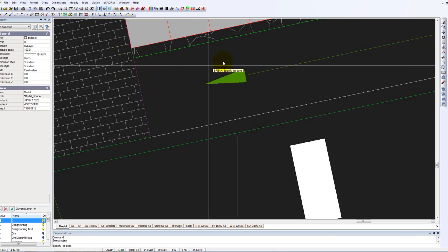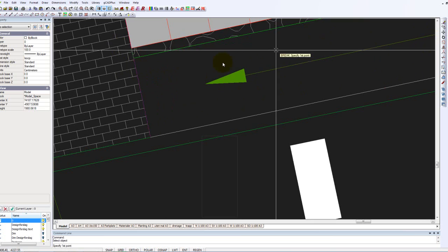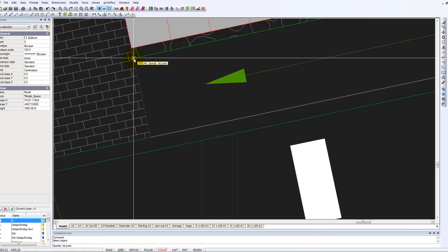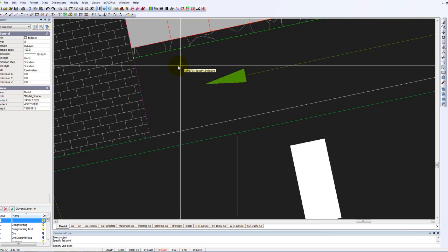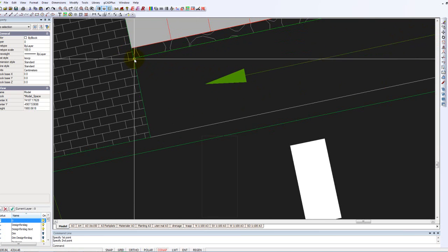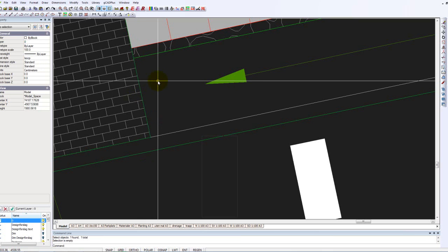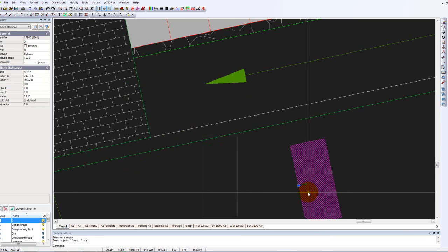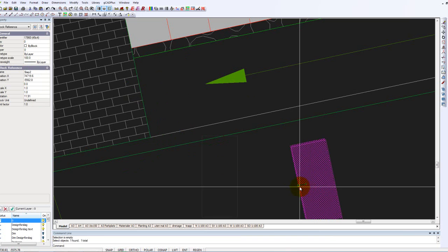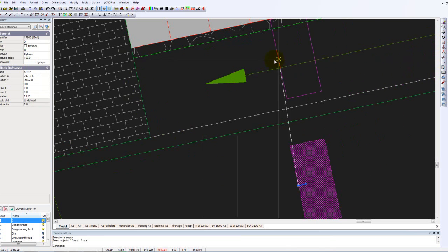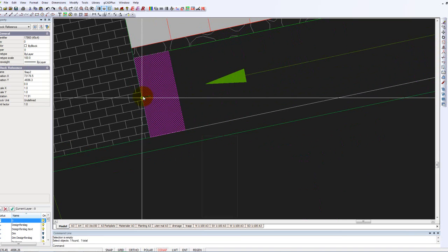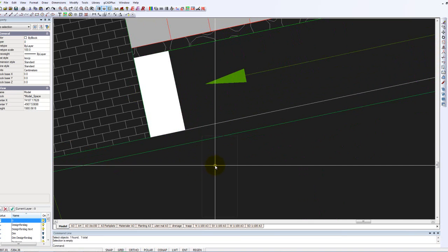The first break point can be the intersection there, and the second break point can also be an intersection there. So now we have the green line that's broken. We can pick our block by its anchor point, and then by selecting the mid O-snap, we can lock that new block into position accurately.